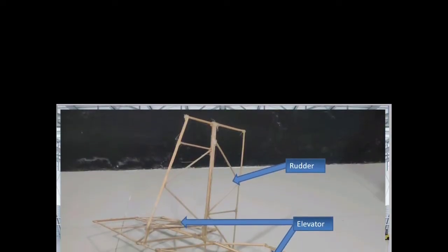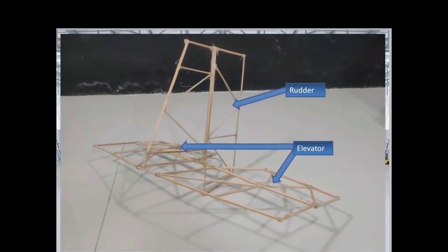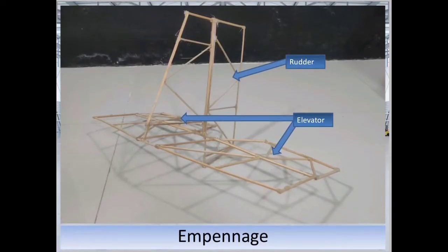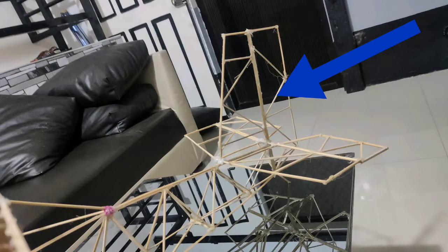The rudder, which is the primary control on the trailing edge of the vertical stabilizer, is controlled in the cockpit by the pilot using the left and right pedals. When the pilot pushes the left pedal, the rudder deflects to the left, pushing the tail right and the nose to yaw left. Using the rudder in combination with the ailerons causes coordinated turns by the aircraft.